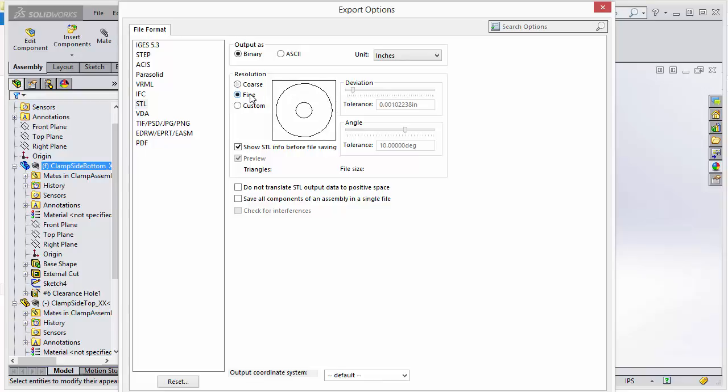And if we go to fine, we see a lot more lines to the point that we really can't see any edges. But also consider what type of design you're printing. Sometimes coarse may produce a suitable model just for doing a rough edit if you're talking about a round surface, but also if you're using a basic shape like a square or a rectangle where you have very little changes, coarse may be suitable for a production prototype to evaluate.